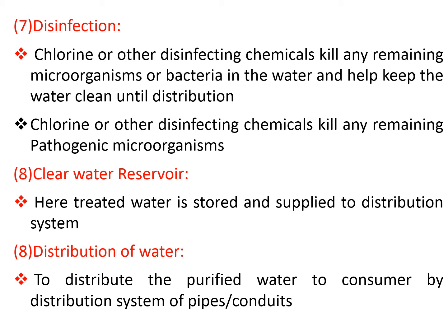After sedimentation, the most important treatment which comes up is called disinfection. Disinfection is nothing but the killing of microorganisms, and for that certain chemicals are to be added. The widely used chemical in India is chlorine, due to its good disinfecting power as well as some residual effect,